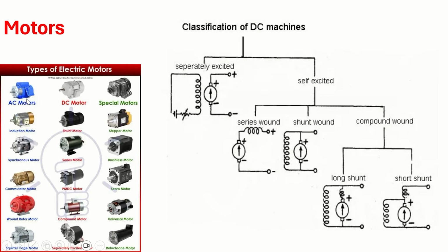They are all based on their stator and rotor design. They are controlled by controlling the AC, right? They may be 230 volts, for example, the sinusoidal voltage and current. When you apply this to the stator, the speed and direction of that motor are controlled by the AC signal itself. So the speed and direction you are indirectly controlling through the sinusoidal waveform.